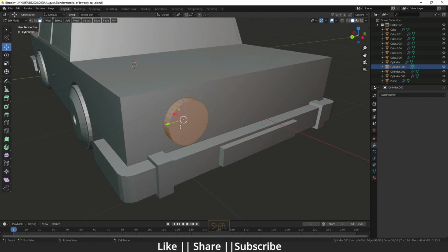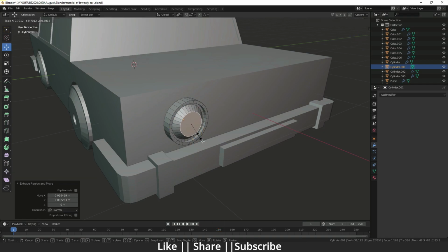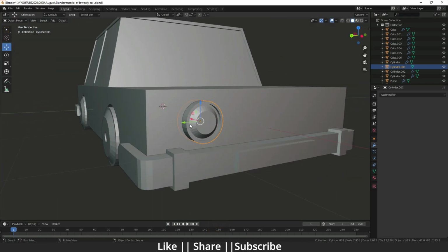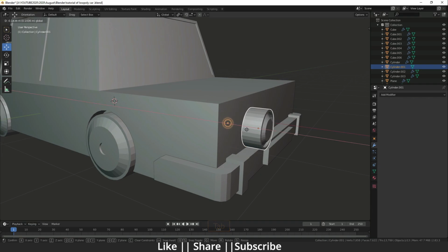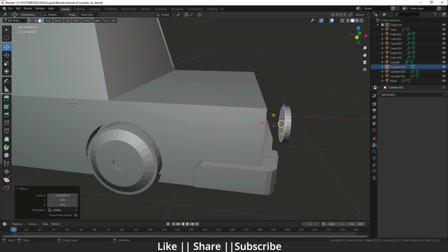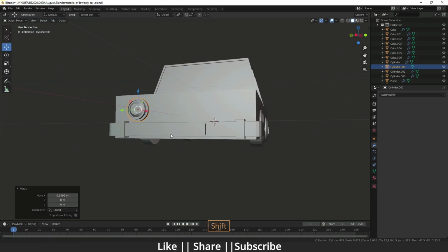Then after that I will go to the edit mode. I'm just going to inset that face, and I'm just going to extrude inside, and again do inset, do extrude, and like that. So now we have a headlight here. This is basically a very low poly headlight. Okay, and if you want to do some editing like that, you can do extrude and scale. So now we have a low poly headlight here.